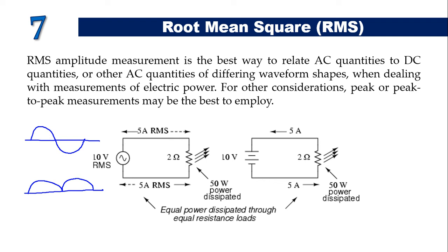So when we speak of the average value of a waveform, the practical average is intended unless otherwise stated. Another method of deriving an aggregate value is based on the waveform's ability to do useful work when applied to a load resistance.